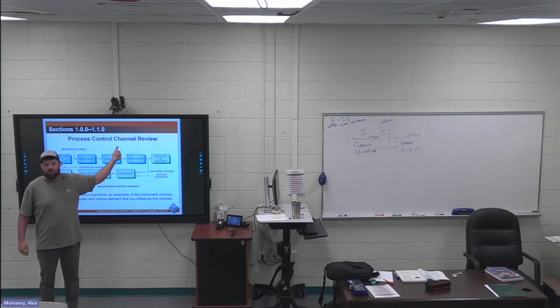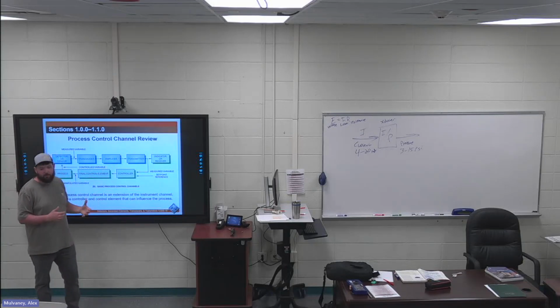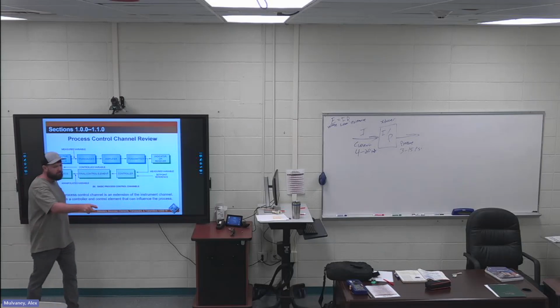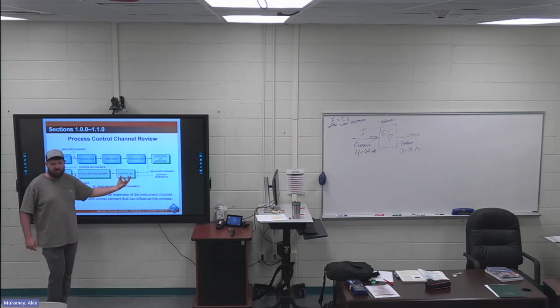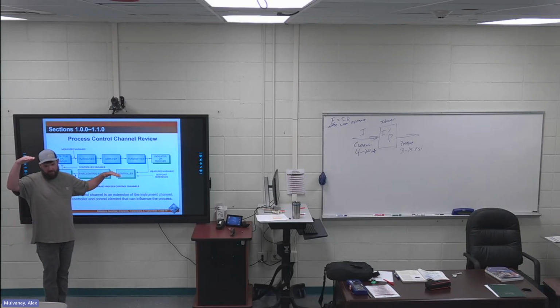It can be a PLC, that big rack that's up there. It can be, you guys started working on these two big blue trainers over here, a PID controller. That's a lot of times what it is. It's the brains, right? So the thermocouple is telling the brains what the temperature is. This is making a determination: we're at 100. You want to be at a 100 degree set point. Say we're at 80 degrees. Not there. So it's going to control the final control element.